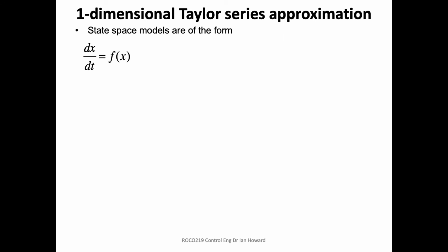We're interested in state space models being first differentials because a state space model is built up of lots of first order differential equations, and we can use lots of these first order equations to represent a high order differential equation, and that's the whole point of state space models.